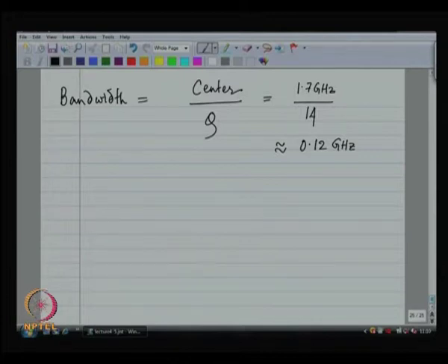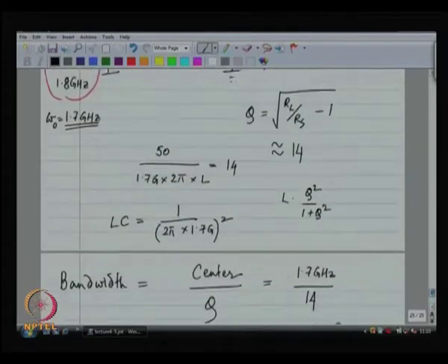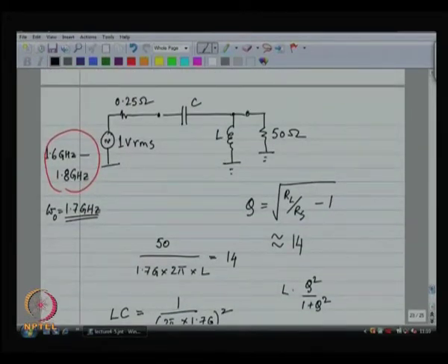right. So, once you start saying that no, I want to have control over the bandwidth over which I should be able to broadcast power, right, then you can't do with this L match. So, the L match has 2 degrees of freedom.